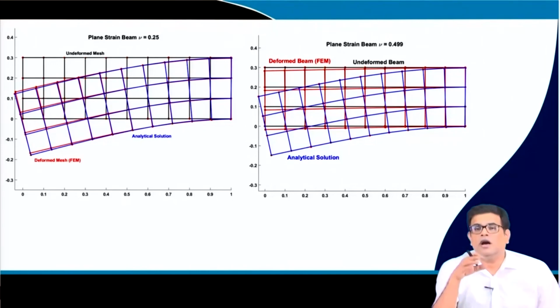In the area which we are dealing with, all materials are actually nearly incompressible. So the Poisson's ratio for a nearly incompressible material in the linear elastic regime is close to 0.5. Now how close it is depends on how many nines there are beyond this point. So 0.499 and 0.4999 will have different implications for the solution technique. I will explain how it is dependent.